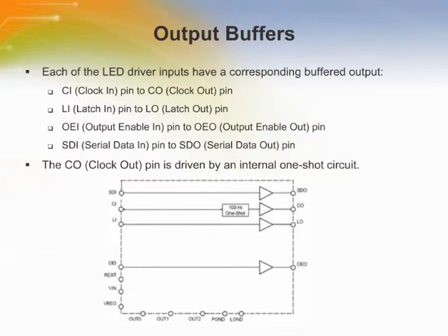The device drives TTL levels. Each driver input has a corresponding buffered output. The clock out pin is driven by an internal one-shot circuit. The one-shot solution produces a constant clock signal throughout the entire driver chain to ensure synchronization of the data line.